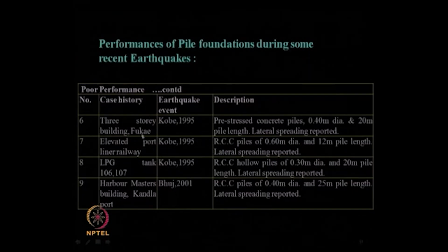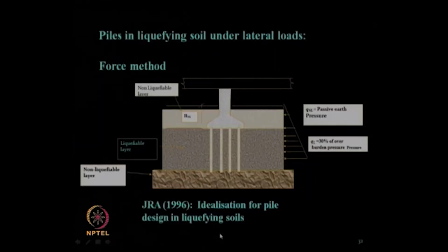So, these are the examples of poor performance of pile during earthquake. Now, how does this pile behave under lateral load and in liquefying soil? This picture typically shows how to do a force based method of estimation for pile foundation design. This is actually proposed by JRA, Japan Road Association, 1996 recommendation, on how to do the design of pile passing